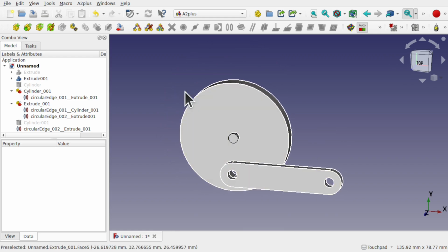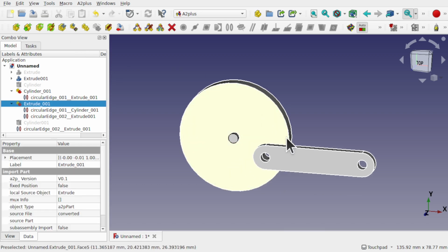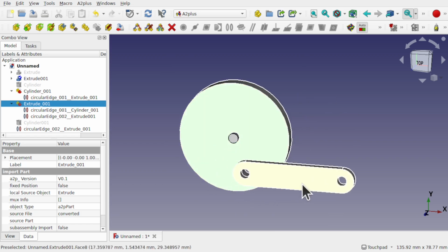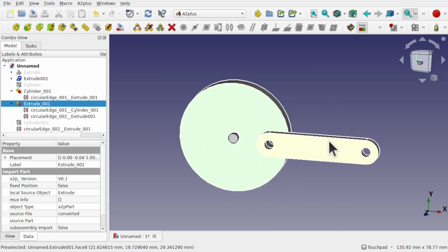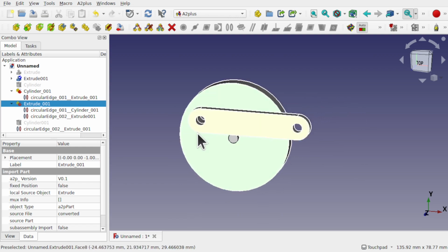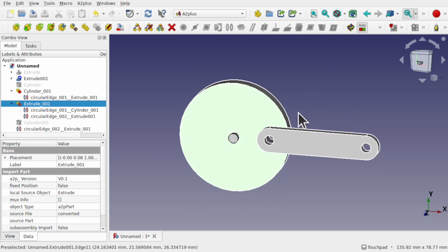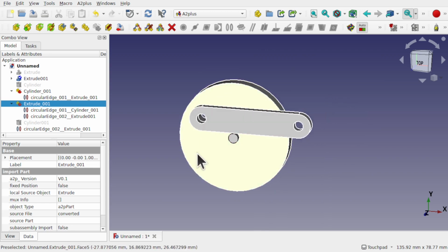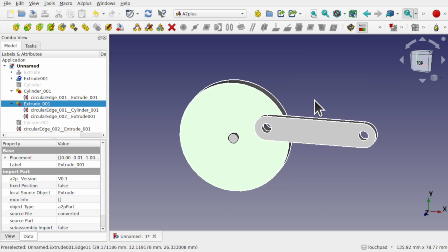So now if I move a part under constraint, we'll see that we can move this around, no problems at all. So we're actually moving this part here, and you can see that the movement will move that wheel, and you can see an edge. See that edge of that wheel? It's being rotated around here.